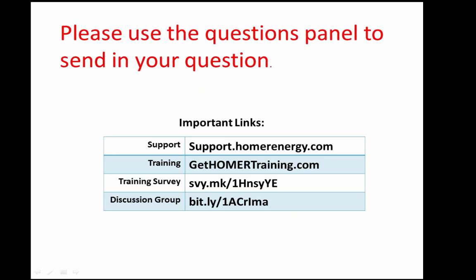Okay. Is it possible to add other costs like buildings, installation cost, wiring, and meters for distribution into your model? Yeah. Under the project button of the system ribbon, there is an option to add in system fixed capital cost and system fixed O&M cost. And that's a good spot to put those sorts of costs that are less influenced by the design.